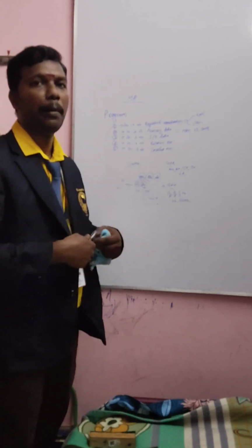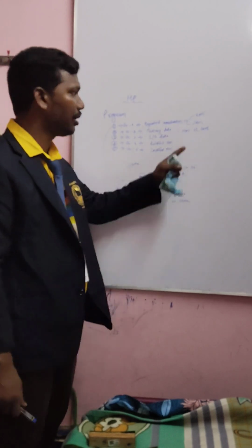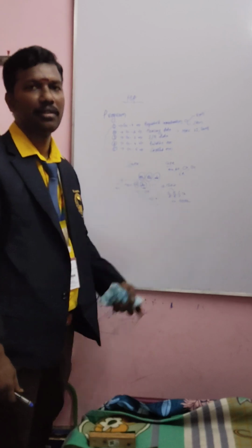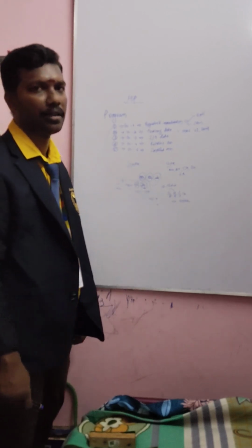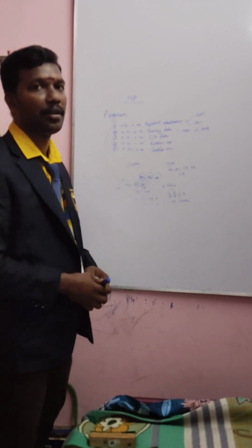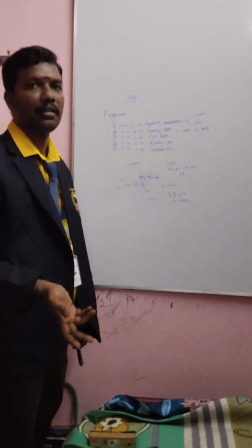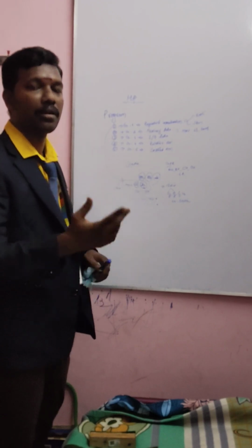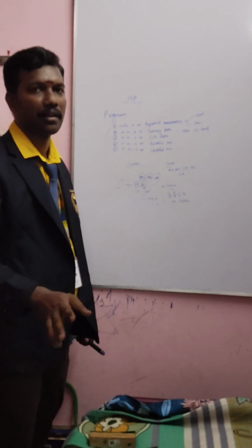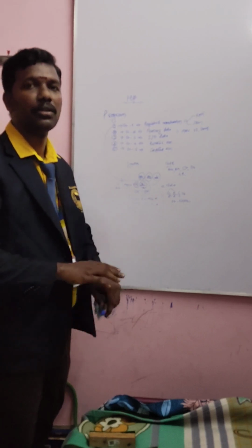If you are moving a lot of data, an array of data, we just move it using SI. What are the other instructions? Instead of SI, we can use DI. So many things we have for memory locations. But there is no possibility of move SI comma SI, or move SI comma DI, or DI comma SI. In the same way, move [4100] comma [4200] is not allowed.